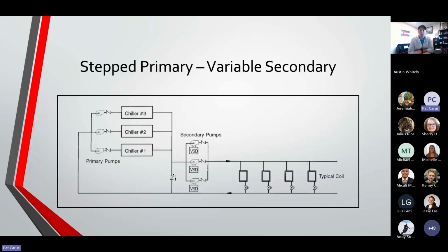I mentioned earlier there's a primary, variable, secondary machine setup. So this one, primary movers, chillers 1, 2, and 3 on the left side, controlled by primary pumps. And then there's a decoupler that runs down about a third of the way through the screen. I don't know if you can see my cursor, but right there, there's your decoupler, which handles the chiller side. And then the secondary pumps manage the push to the air handling units to the building, or the load side of the operation.